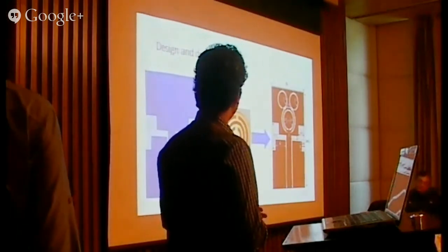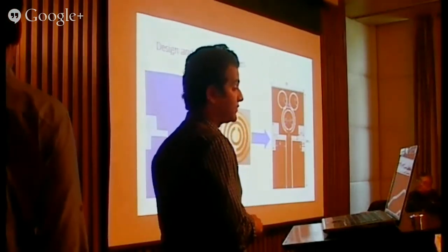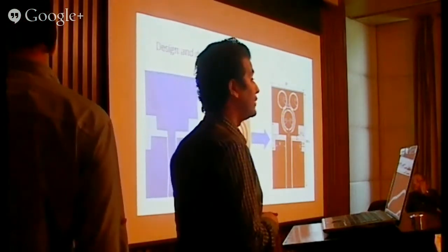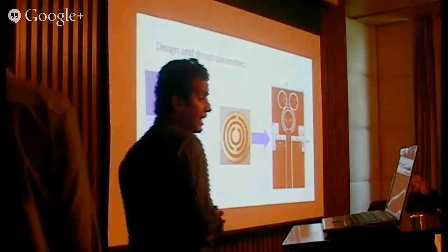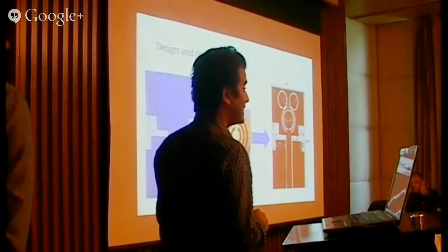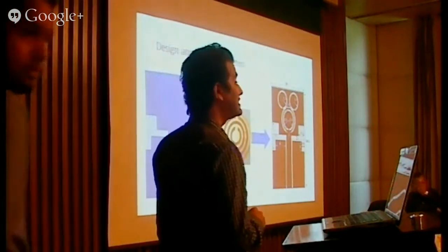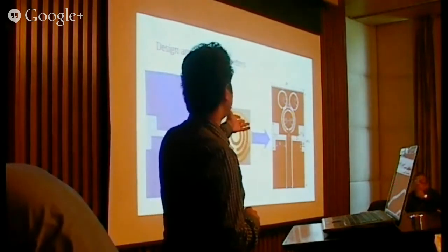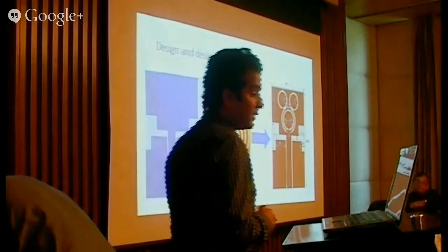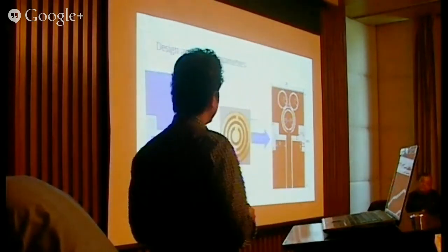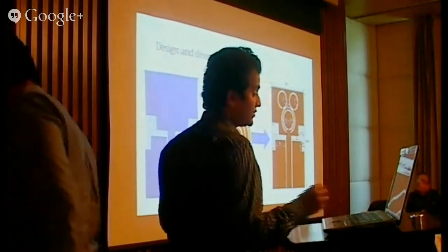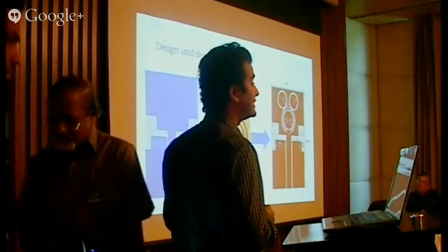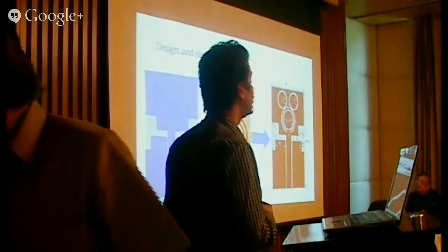This antenna has already been modified once by me for dual notches in Wi-Fi and WiMAX. Now, the term I have used here is CSSRR, complementary single split ring resonator. And I have modified it to overlap CSSRR. Now, to modify this antenna, I make it a resonator so that we could get more characteristics. For putting in a resonator, the size is a restriction because this design has already been matched, and now I have to modify this one.